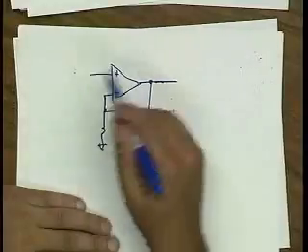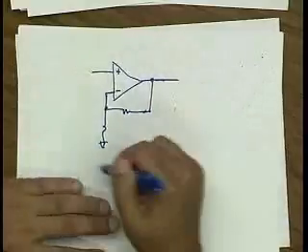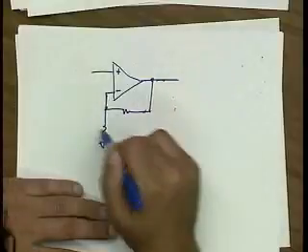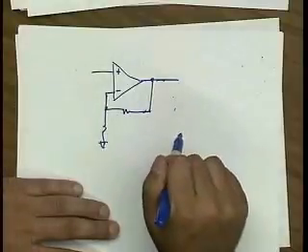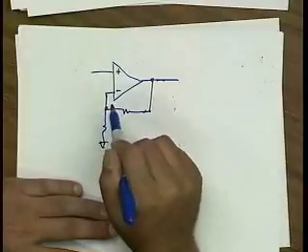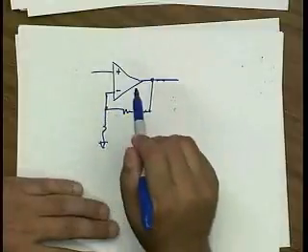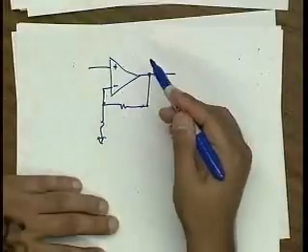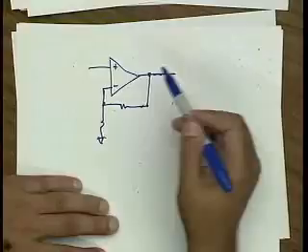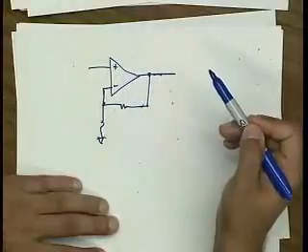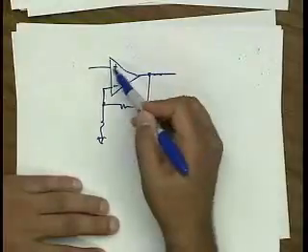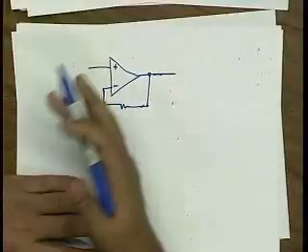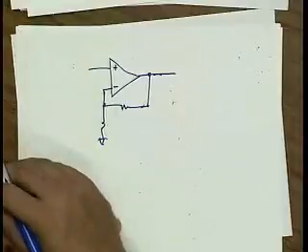Another way to look at it is the feedback system is correcting for the nonlinearity produced by the amplifier, because the feedback system only works with the fundamental. It's comparing the output fundamental with the input fundamental, and any difference is getting rejected. That difference could be due to the finite gain of the amplifier, or it could be due to nonlinearity. So the nonlinearity terms look like extra error terms that the feedback system is trying to get rid of. So that's a little bit of intuition on what's going on.